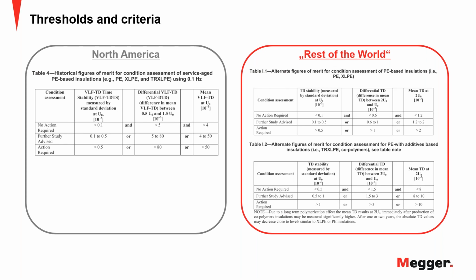Also, just to add, in terms of talking about leakage current, there's a difference between the waveforms. You can really just measure leakage current with the cosine rectangular. For a sinusoidal test set, leakage current is not defined. You can only get a charging current, which is not the same.